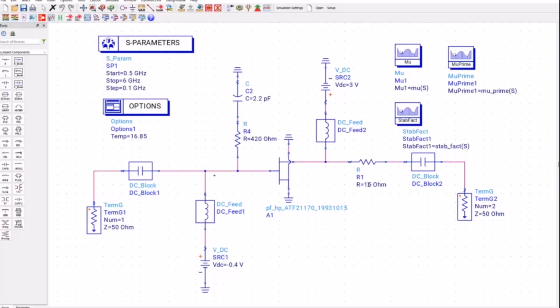If you are doing a power amplifier, you will do exactly the reverse thing. To stabilize this device, you will put this resistor at the input, because in a power amplifier this signal will be very high, and you don't want this resistor to eat away the power that you have achieved after a lot of struggle. So putting this resistor at the input will be a much better choice. So here, to achieve stability, I also had to put a resistor capacitor network at the input. But here you can see I have put a much higher resistor to minimize the impact. I needed to do this in order to achieve broadband stability on this transistor.